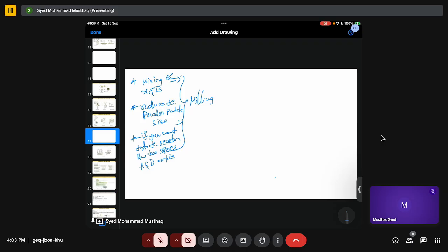So this energy is coming from the collision between the powder particles and balls. Now, if you do it at low RPM, the energy is not very large, it's small, so there is not even breaking of powder particles. So that's why we do the mixing at max 80 to 90 RPM, rotations per minute.